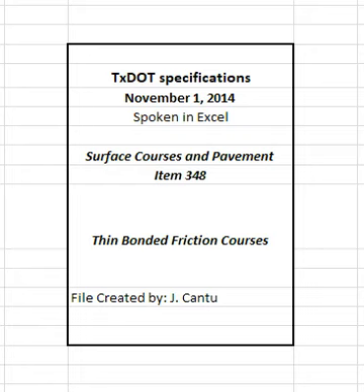4.4.2.1.13 Trial batch sampling. Obtain a representative sample of the trial batch and split it into 3 equal portions in accordance with Tex-222-F. Label these portions as contractor, engineer, and referee. Deliver samples to the appropriate laboratory as directed.